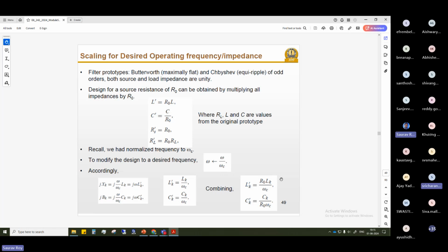So by the way, all this last theory work, the last slide, whatever is currently there, you're telling the process of taking the tabular forms for the particular Butterworth or Chebyshev filter, like the coefficients provided in the Pozar book, and converting them into realizable L and C values to construct an actual filter. Yes, right.